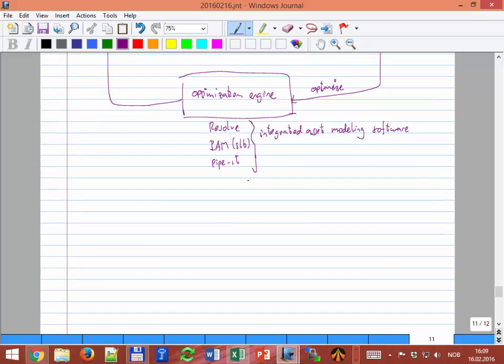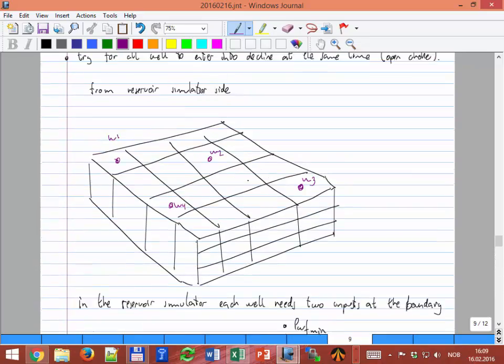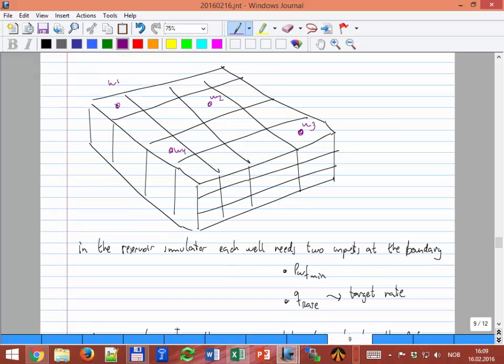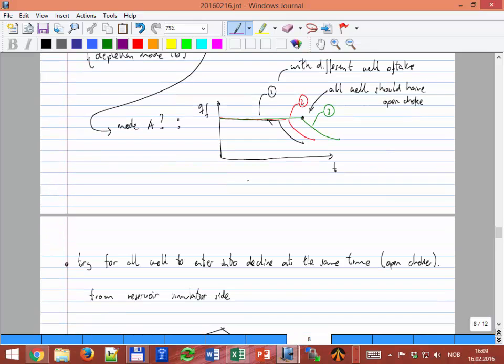And this potential idea, you can have it either from the reservoir simulator, which for big fields is how it's done, but for small fields maybe you do it by well test. You test the well open, no choke, you get the maximum rate that it has, and then you do the same thing. You do the splitting, calculate the splitting factor, and this is the factor that you use to allocate rates. Is that clear? Yeah.